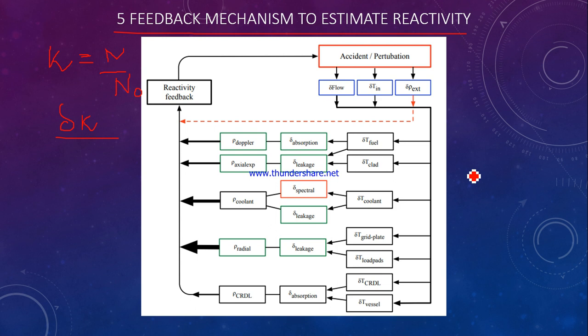So this is structural. If there is a structural change, then in turn the density of the fuel will also change. And then the absorption changes, because in Fick's law you will be seeing the concept of macroscopic cross section. So this macroscopic cross section will change, which will change the delta K. But the reactivity change is based on the structural change, and there is no direct mechanism to measure the strain of the structure inside the reactor. The only parameter in our hand is temperature. So temperature monitoring is very important in a reactor for its reactivity control.